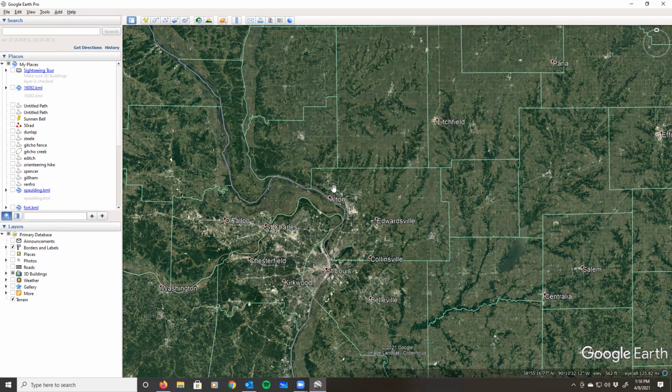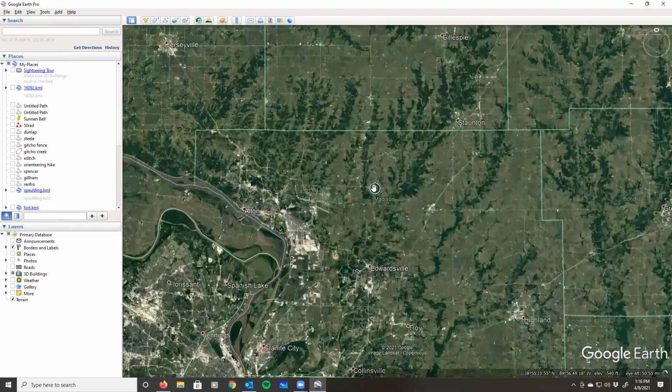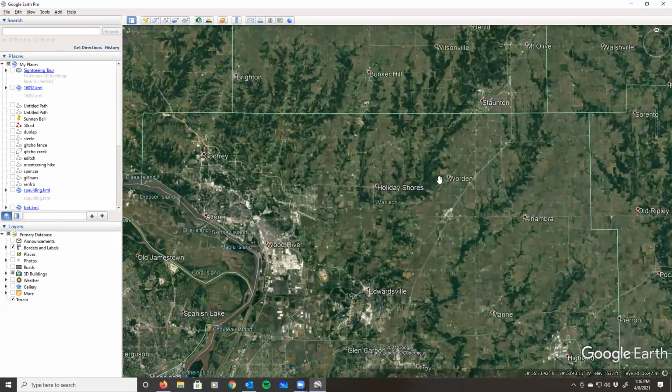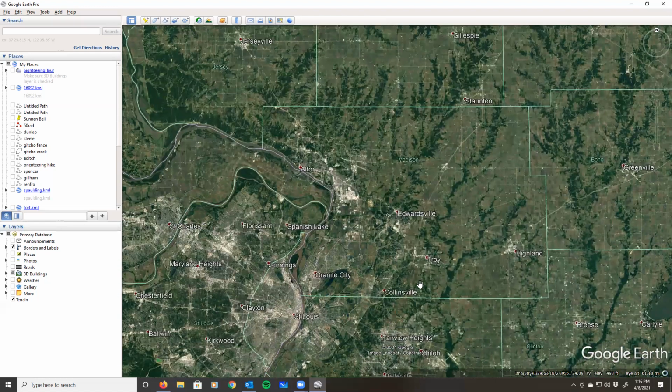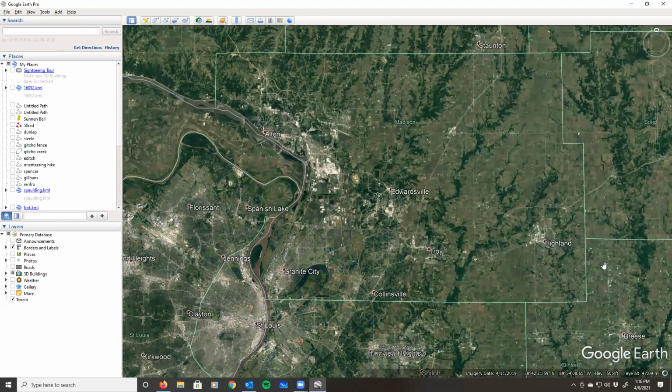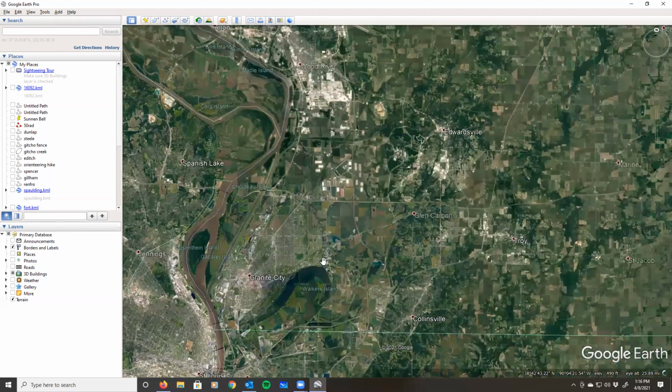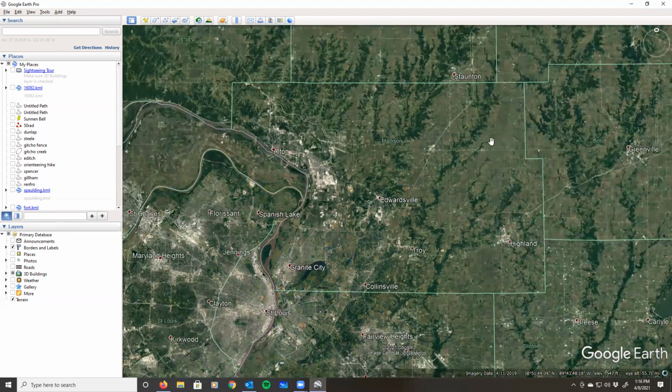The areas where the scale factor would be very close to 1 would be passing 1/6 of the way in from the northern edge of the county. So it would probably be in the area of Worden or Holiday Shores. Likewise, probably just south of Troy would be the 1/6 of the area in. So through Granite City, the scale factor would be 1. And because the county is relatively flat, plus or minus maybe 150 feet at the most, I would think.